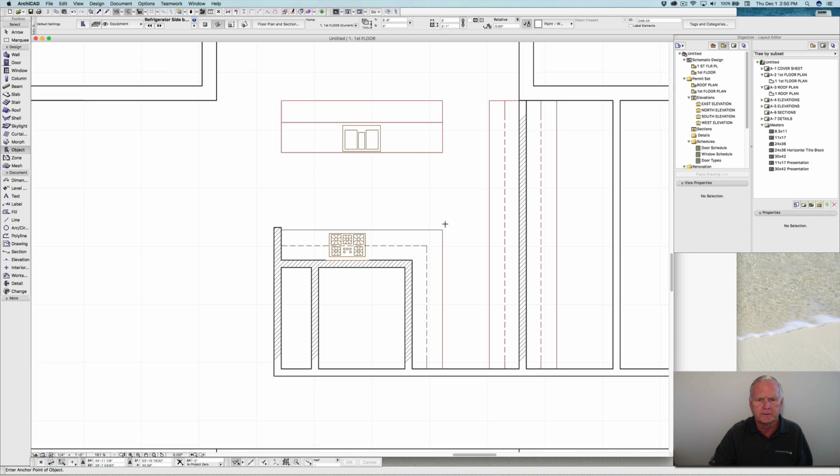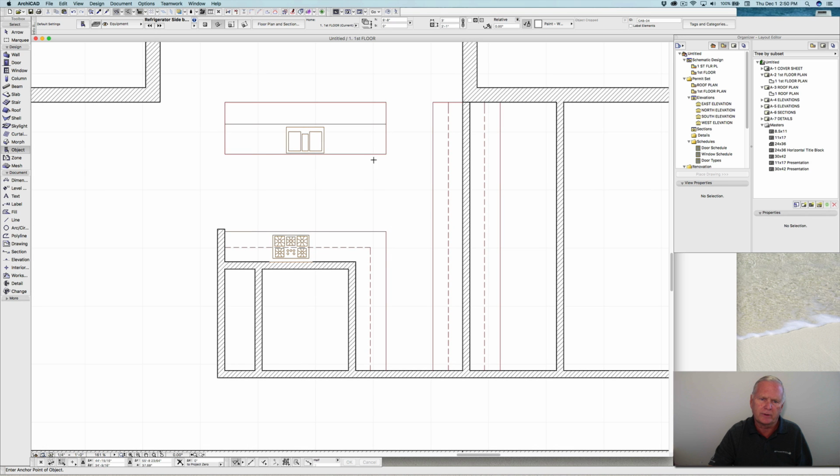And then I want it on this, and I want it in the middle of this. So as I look at that, and I kind of want to see how far this is, we're going to use the measure tool. Click on here, click to there, and that's 5 foot 4. That's probably okay. Not a bad distance, plenty of work room there. So we want to be on the center line here. So our center line of 5 foot 4, of course, would be 2 foot 8. We'll grab a guideline and go D, 2 foot 8, and go enter, and then that gives us this guideline and this intersection point, and we can spin a refrigerator into place, and we have our refrigerator.